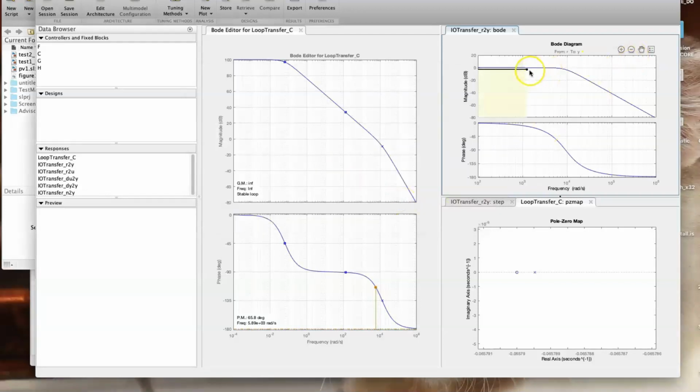Alright, so we have to make sure that the closed loop bandwidth is going to occur at that frequency, which is at 1.256, which means that the gain of the closed loop has to be minus 3 dB at this closed loop bandwidth by tuning using this loop transfer function for the speed. And again, if I add a PI controller, then I will add 3 elements, which are a DC gain, an integrator, and a 0.